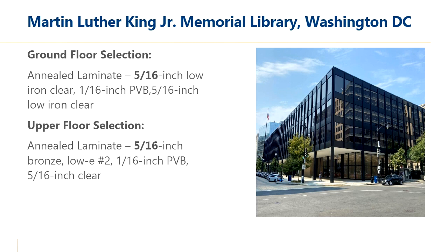Per Mark's comments, they did decide on an annealed laminated glass for both the lower and upper floors, despite the lower thermal performance and lower strength versus the heat-treated options. They decided that the presence of the low-E coating on the upper bronze lights was okay. They thought that was visually acceptable. So they were able to decrease solar heat gain at the majority of the building glazing.